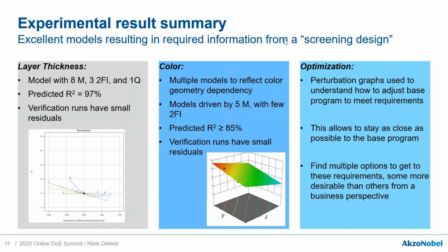And this is a very nice feature in Design Expert, where you can highlight a few of the runs as verification runs. They are not included in the model build, but they are then, for example, shown in the graphs, and you can do diagnostics to see how well they fit in the built models. That's really a useful tool, and especially if you do these very small, efficient designs, it's good to add them so that you can directly verify whether the models that you've created make sense.